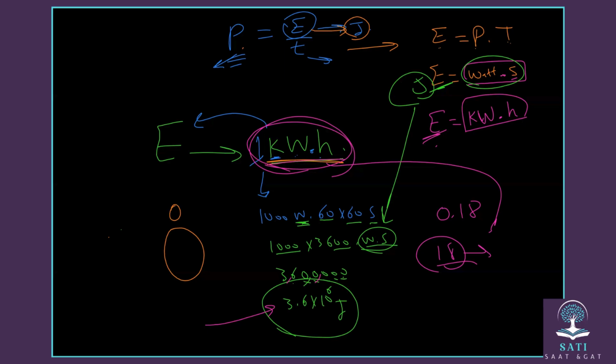So to send electricity over a long distance, you need to decrease the resistance, and decreasing the resistance means decreasing the loss of energy. And how do we do that? By choosing good materials for the wires when they are manufactured, and also we increase the cross-sectional area of the wires, and we increase the voltage as well.